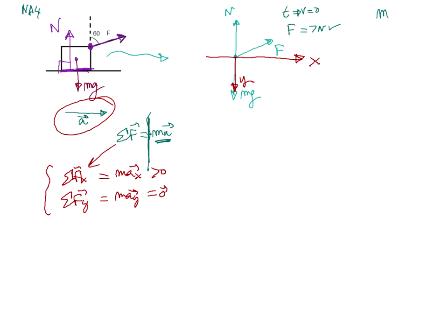We need this to express, I'm going to call it alpha, F in component notation. Because by identifying the direction, now it's easy. We know that the x component of F is sine, positive, and the y component of F is cosine and is negative. If we hadn't done this step, we'd be toast.